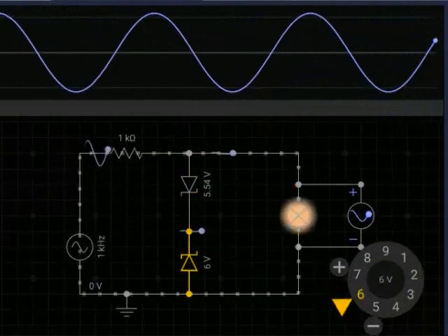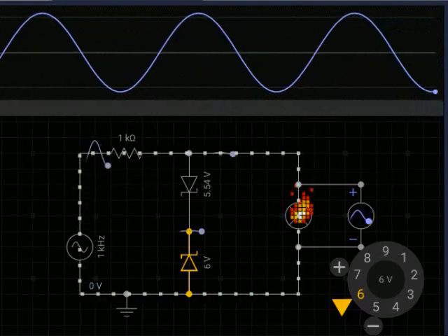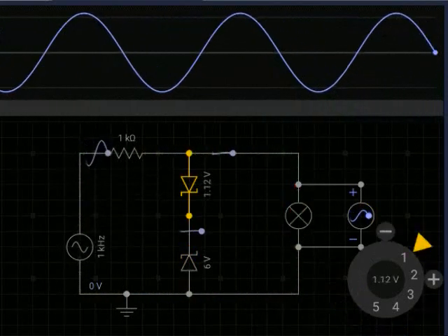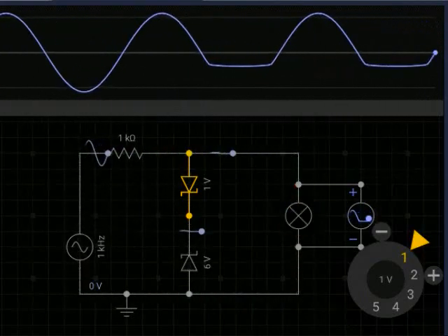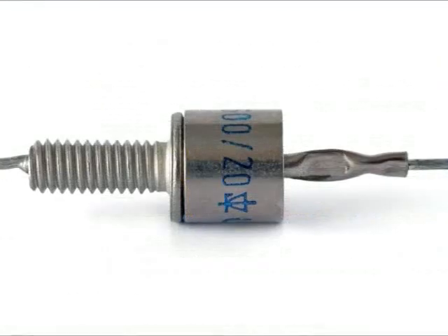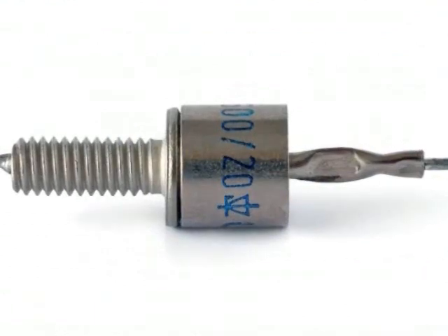This breakdown voltage is known as the Zener voltage, and it will be from 1.7 to 200 volts based on the structure of the diodes, which is used as a voltage reference in circuits. Zeners are used for signal clipping, shifters and voltage regulators.